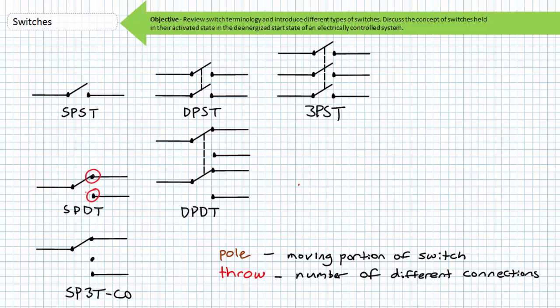An application for a single pole double throw switch would be to de-energize one load at the same time a different load is energized. Additionally, one could use a single pole double throw switch to selectively supply a single load from two different sources. Consider a subtle modification to the single pole double throw switch by including a stable center state in which no connection is made.